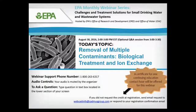With that, the first question will be for Dr. Boyer. You showed a little bit of DOC removal with the cation exchange resin. What percentage of DOC has a positive rather than negative charge? Yeah, that's an interesting question. From my experience, the fraction of DOC that would have a positive charge is very small, maybe on the order of 10%, but that's a number I could try and get a better answer for. From all the work we've done, the majority of DOC is negatively charged, and from the different experiments we did, we believe that it's the negatively charged DOC that was being removed by that cation exchange resin due to that iron oxide component.